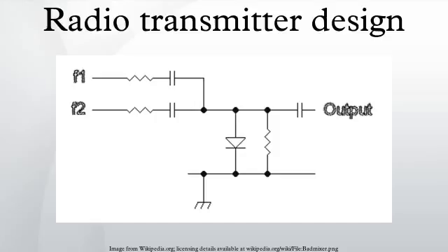Amplifying the signal. Valves. For high-power, high-frequency systems it is normal to use valves. Please see valve RF amplifier for details of how valved RF power stages work. Valves are electrically very robust. They can tolerate overloads which would destroy bipolar transistor systems in milliseconds. As a result, valved amplifiers may resist mistuning, lightning and power surges better.